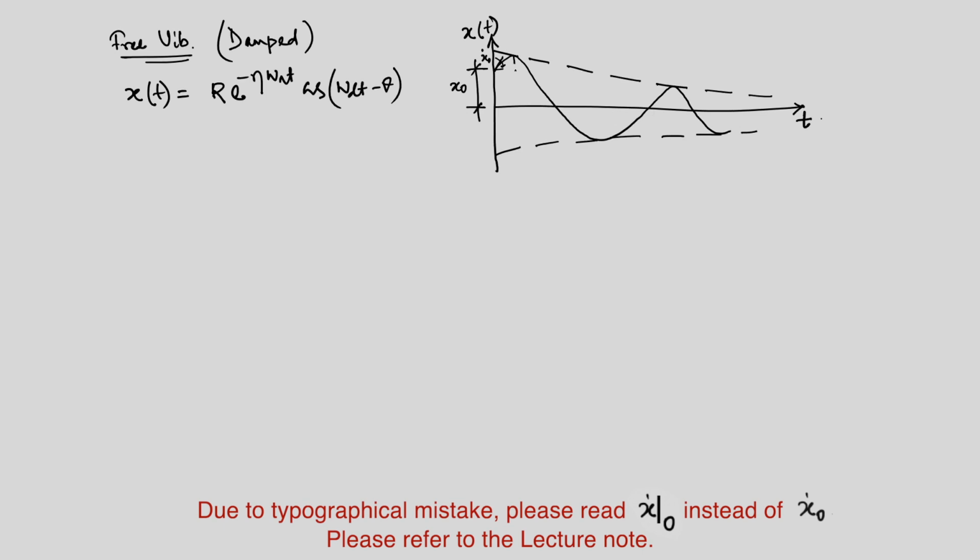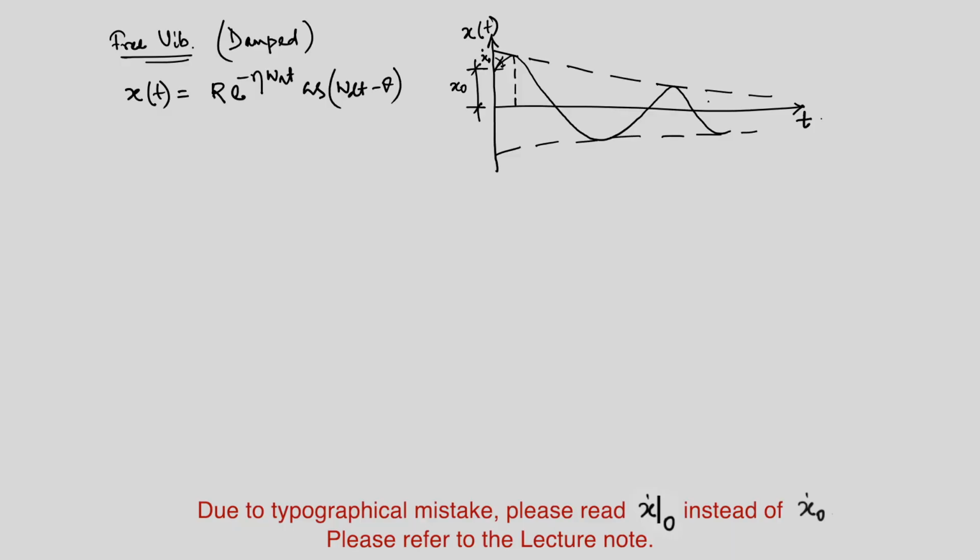Now, let us consider this response. Just imagine if we have a SDOF system and we can measure the displacement of that system, we basically get this plot. Now, from this plot we can identify the structural parameters. What are the structural parameters in this case? We have natural frequency, we have critical damping ratio. So, let us see how we can evaluate that.